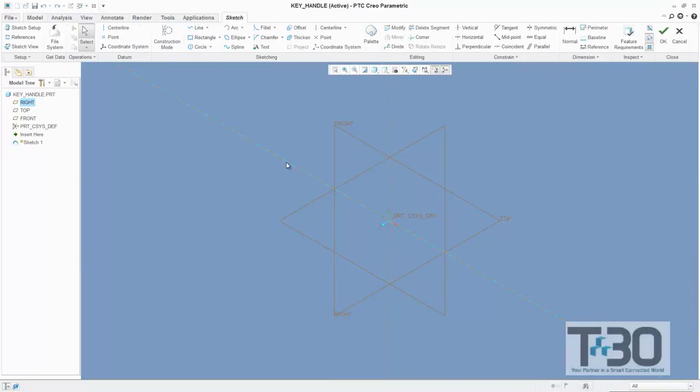So now you see a little sketching section come up. This indicates that you can begin sketching, and we can see the different shapes we can put on this bar. So if we choose circle, go ahead and sketch out a circle, and middle mouse click, the dimension of this pops up. And as you can see, it says it's weak, which means it hasn't been identified exactly what it should be.